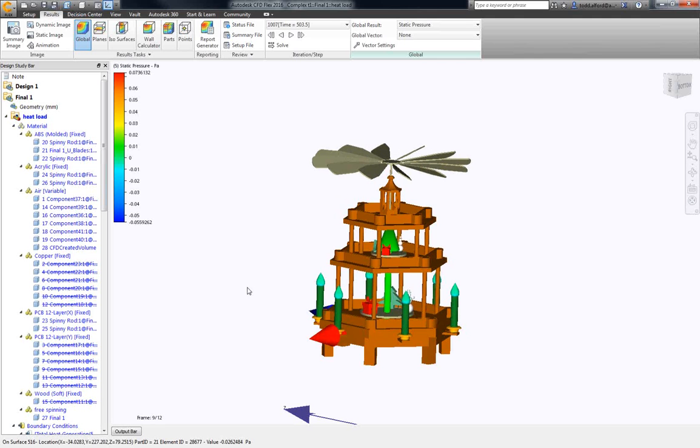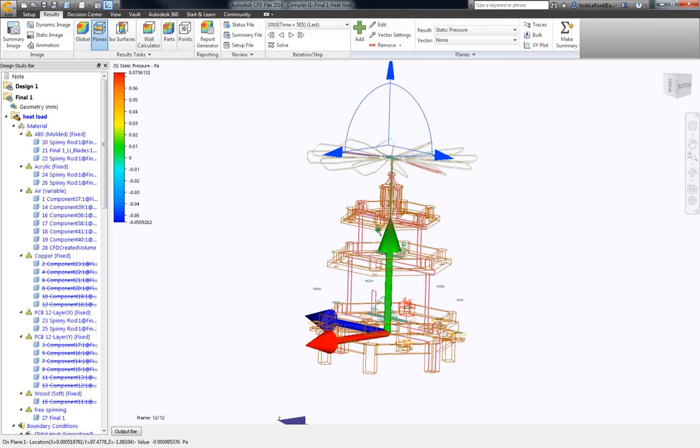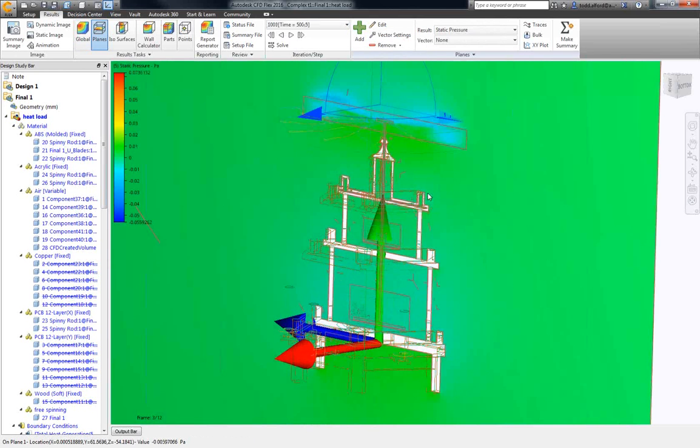With our CFD code, we solve the nodes. So in reality, we want nodal points. So if it's tetrahedral or hexahedral, the hexahedral actually doesn't really help us in terms of solver quality. That's my understanding, at least, without being a solver programmer. So in terms of our code, it doesn't really matter. We do have more than just tetrahedrals, though. We also have prism elements or wedges. That's actually what defines the elements along the walls of geometry, and Todd can show that. So I hope that answers your question, Artur, about the tetrahedrals and things like that. We have explored that in the past, and it just hasn't been necessary.